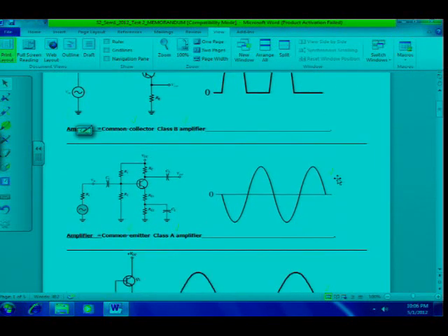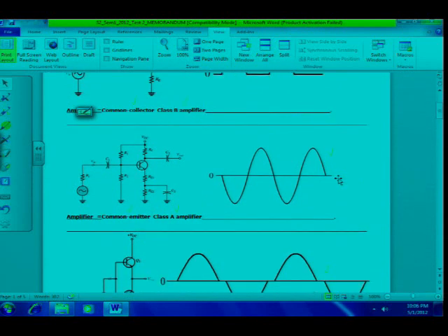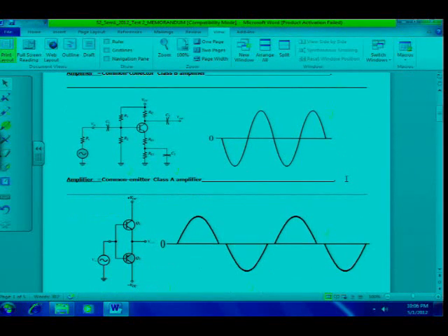Alright, the second one, the amplifier that we started off this semester, common emitter. If I look at the input and the output, and I can see it's biased, it's voltage divider biased. So it's, most probably in this case, a class A amplifier, linear amplifier, and I can see my 2 waves on the output shown there. So replica of the input signal, only it is amplified.